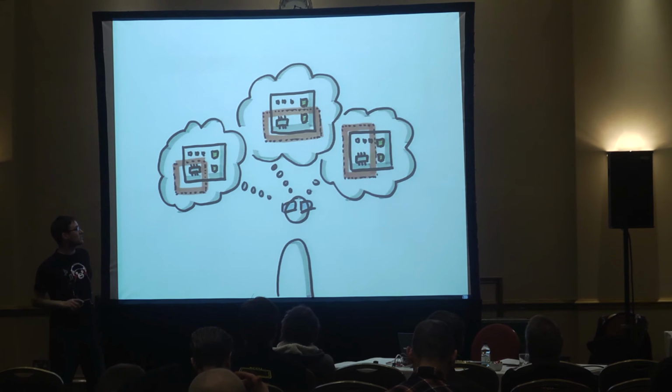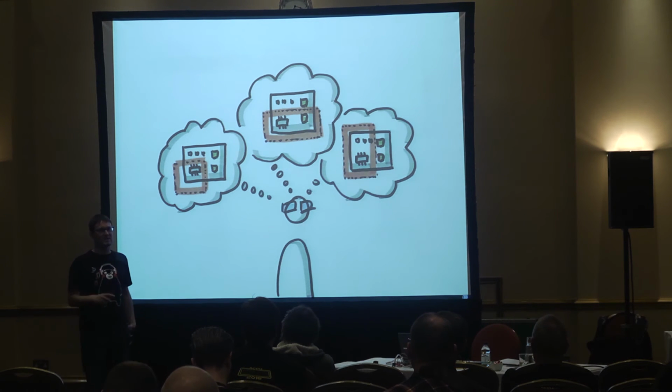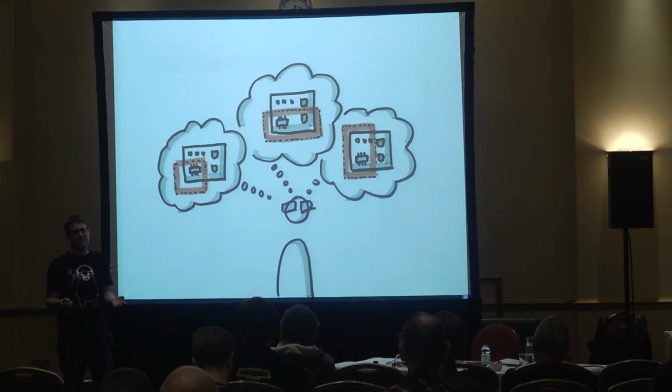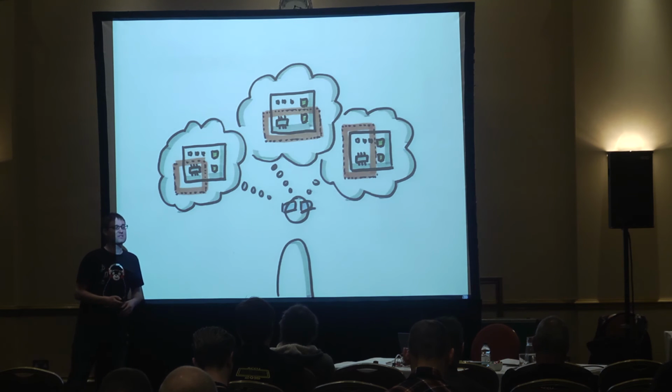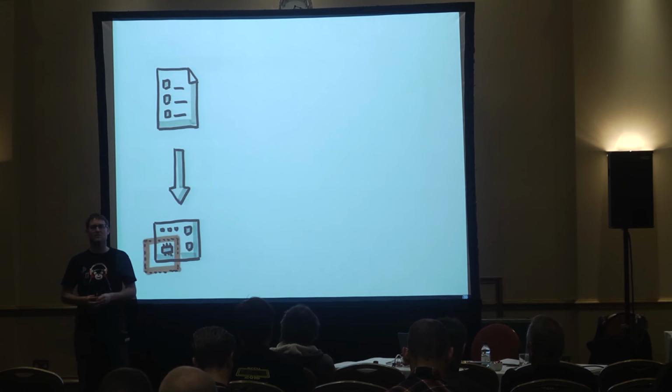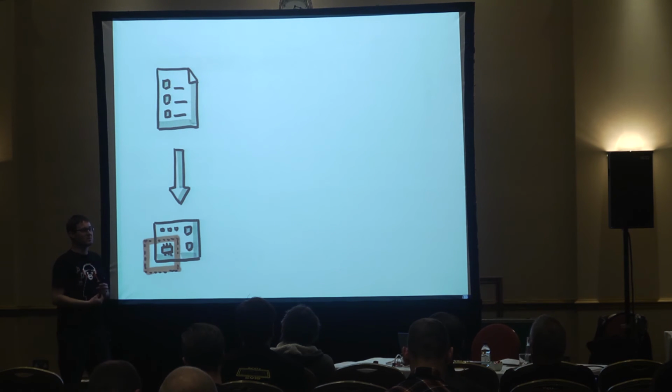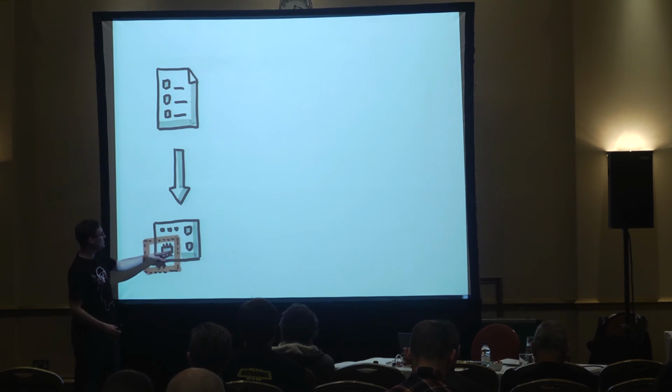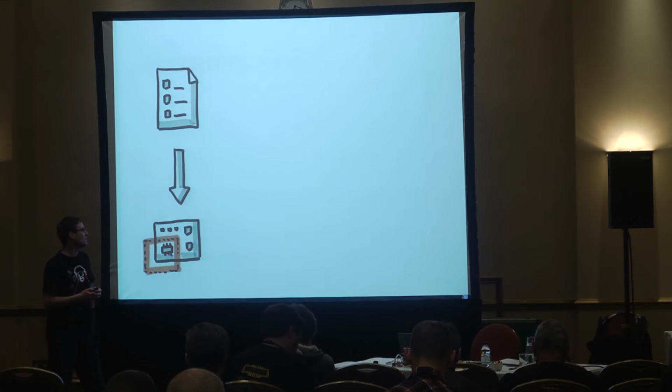A second thing which is also special about embedded is you have to find out where to cut your testing boundaries, what I said before. Should you have a test double for the GPIO? Should you go until the IO mapped registers? One strategy to find it out, especially if you start with acceptance tests first, is this: especially in the beginning, if you start with a new system, you do not have that much knowledge about what you want to do, where it's going to go, or even how your hardware works. So I set my boundary quite on a high level, maybe just on some higher level software components, and abstract more or less all hardware with test doubles.